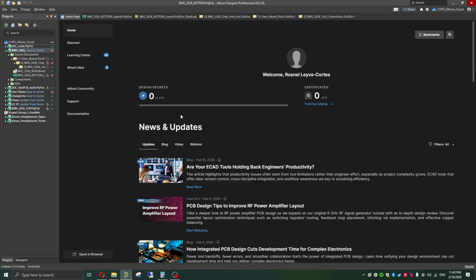It's a pretty good point of mitigation because when you're using a breadboard, there's a lot of parasitic capacitances that are just induced by the nature of the geometry of the packaging, and in a printed circuit board you have very precise control over the different layers, the dielectrics, and all sorts of different things that just make it better overall. So you definitely want to consider this to create a nice polished final product for whatever circuits your team is designing. For context, I have some example circuits.